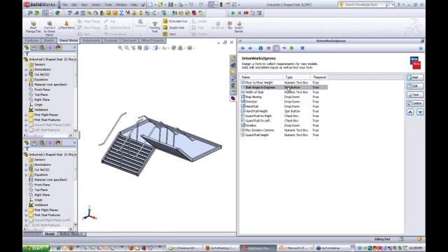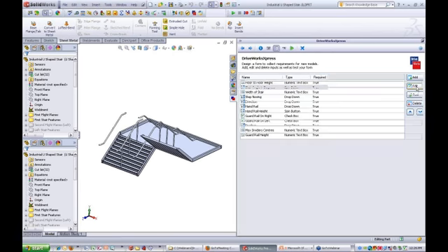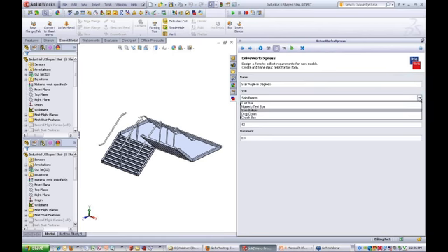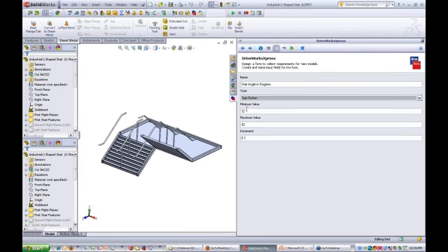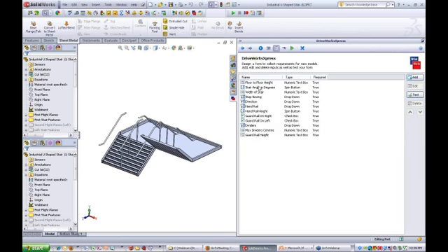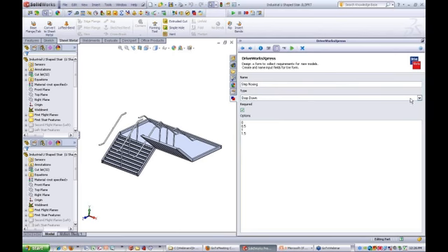The stair angle in degrees was the spin button. Just edit that one. So there's a spin button selected with a minimum and maximum value and the incremental value as well. And so on. For example, the step nosing is a drop-down box. So we can edit that, and a simple drop-down box has been selected. And here are the values that can go into that drop-down box. So this is how you control the data that can be selected and limit any data entry errors.